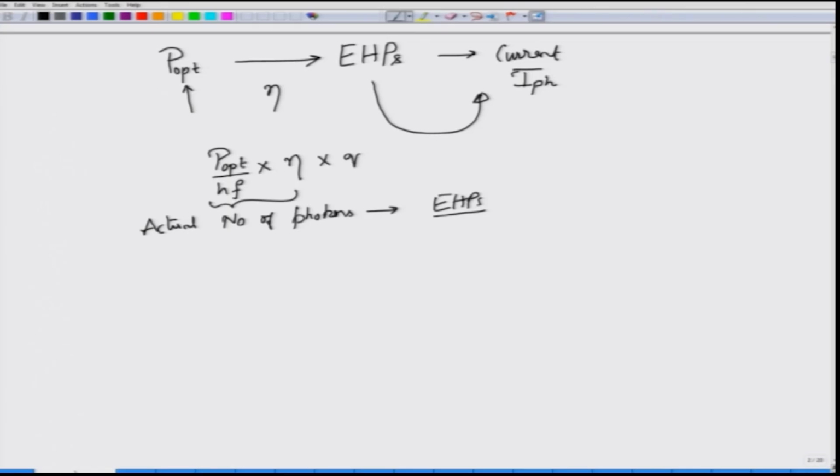Okay. So, if we do not want to distinguish all that, we can simply say that eta will be the fraction which tells us the optical power relative to the actual amount of photo carriers that are generated. This would be the amount of current that we actually measure on the output circuit, right. This photo current to the optical power ratio is called the responsivity of the photodiode.